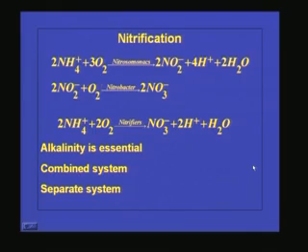So, the second rise is because of the nitrifying bacteria. The initial carbonaceous oxygen demand will be removed first, then the nitrogenous oxygen demand will be exerted by the nitrifiers, which are autotrophic microorganisms.